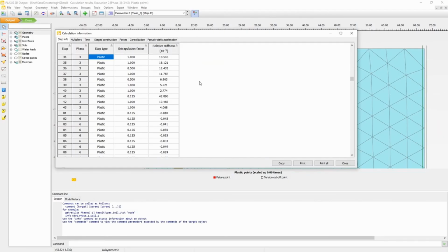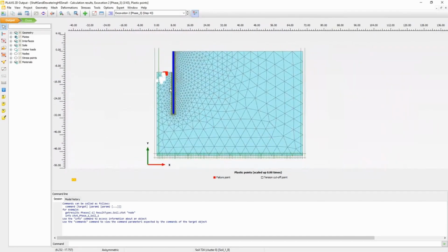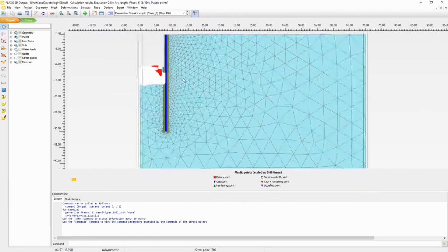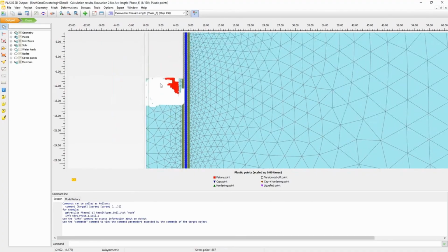That's what it means. And then look at what we observe when we start looking at the same inaccurate plastic point, but looking into that last phase. And then it becomes clear. I mean, we are forcing the soil to get into tension here, which cannot be solved, okay? And the reason for that is very simple. We have pore water pressure here, which starts to pull due to the gradient we still have. And here there is not enough weight to compensate. There is no way you can reach equilibrium, okay?